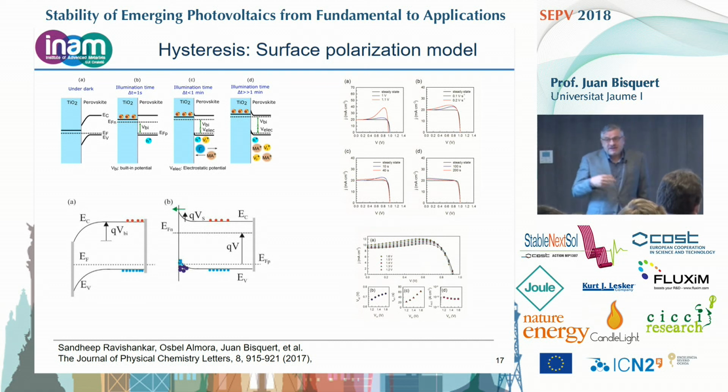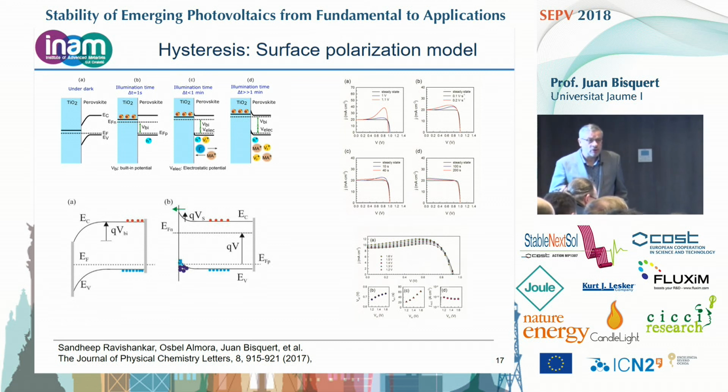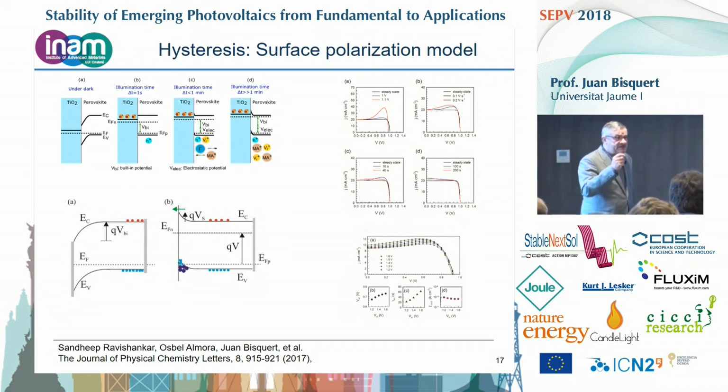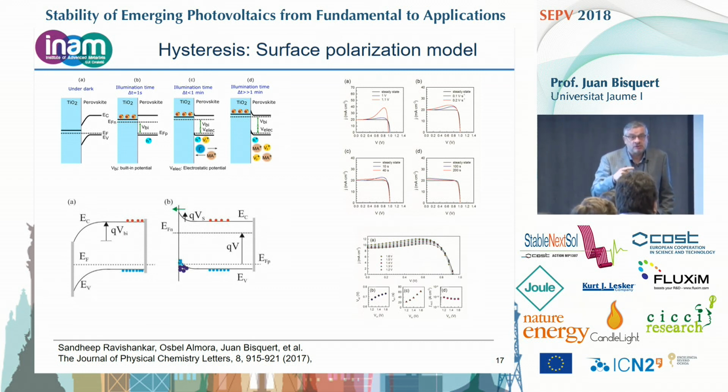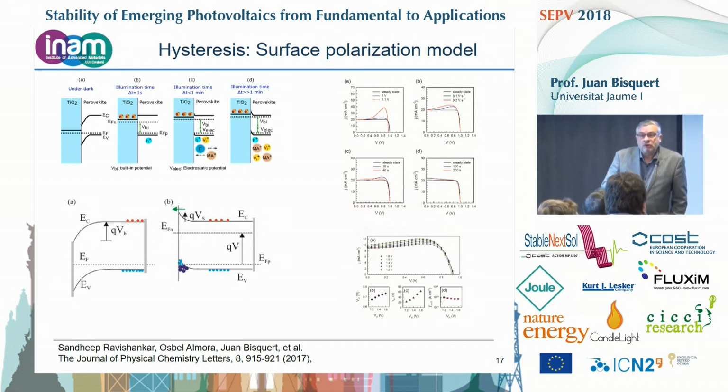So now this starts to explain the complex dynamical phenomena of the perovskite solar cell, because you are calling a lot of electronic and ionic charge to the interface, and they have very different response times, because the ionic diffusion coefficient is something like 10 to the minus 12.